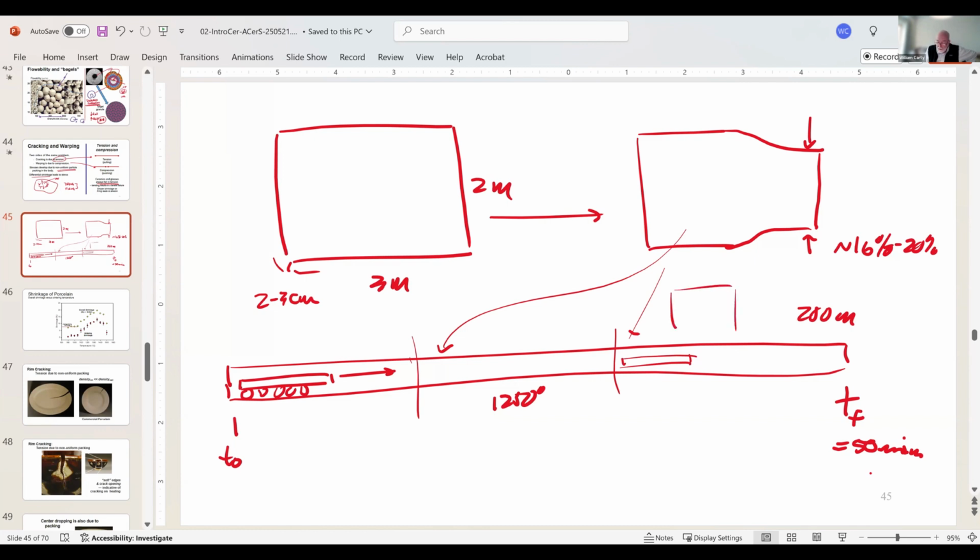It's now its final, it's 2 to 3 millimeters, or meters, excuse me. Okay, so if I take 20% of this, this is actually about 3.6 meters large to start. This is about 2.4 meters large to start, and it gets to 2 meters and to 3 meters with firing. That piece deforms and shrinks one end before the other end is even hot. And we can't rectify that with the idea that I have firing problems that are associated with the material. That means that it is due to packing.